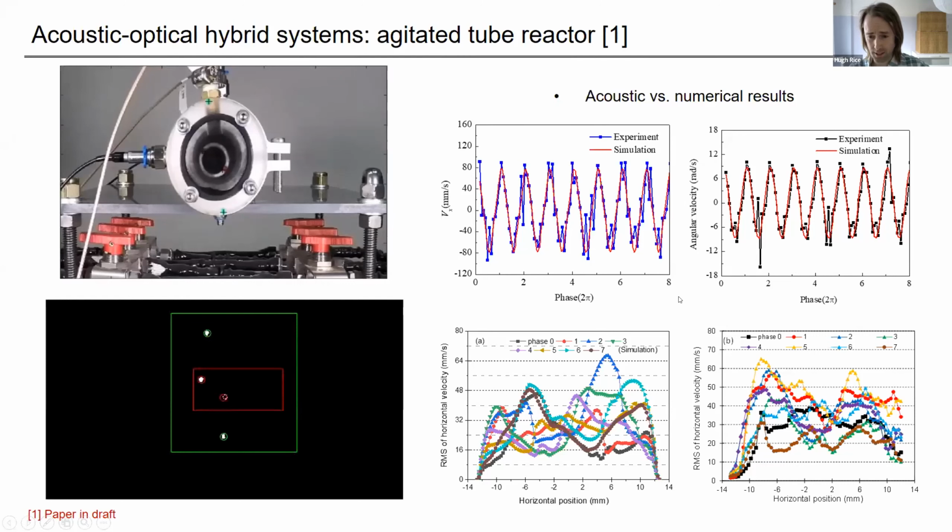And the lower part is the acoustic part. So again, I used an acoustic probe, which you can see in the picture on the top left, attached to a clasp, to measure the RMS velocity, which is the root mean squared, which is a measure of the turbulence intensity across the horizontal cross section of the pipe.